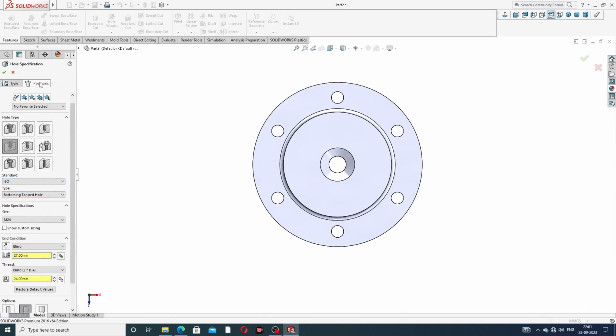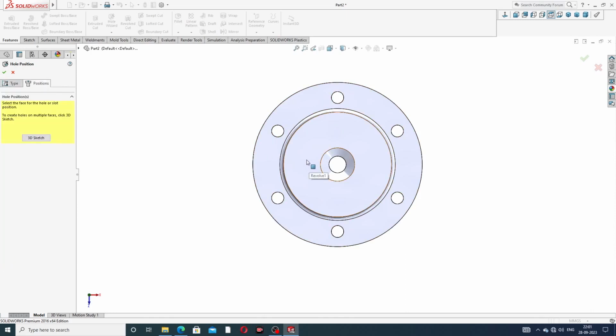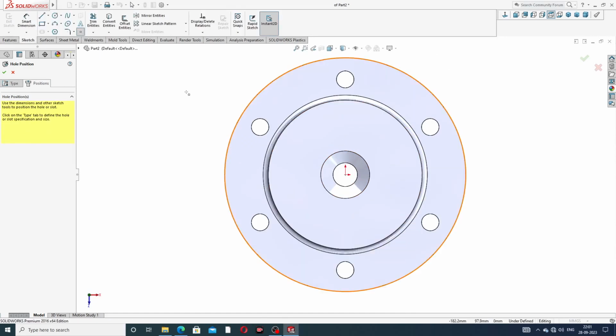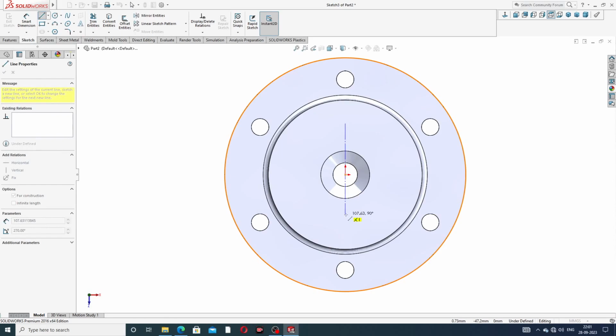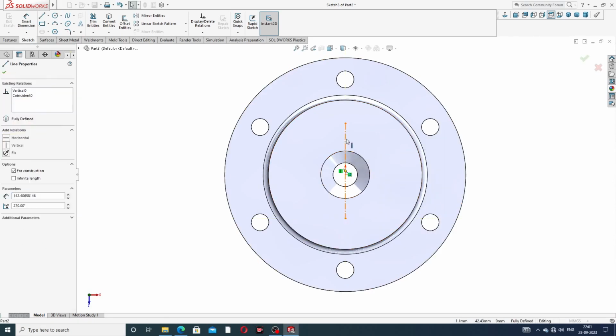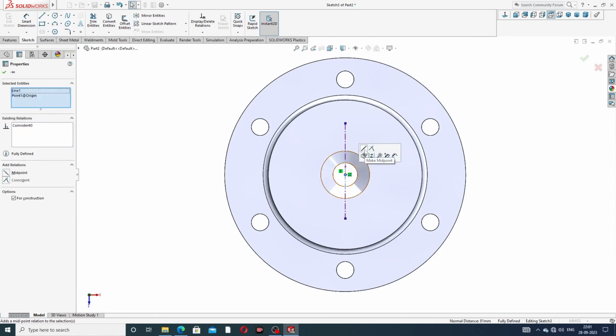And going to position, and this is sketch normal. Okay, and draw a reference line. Reference line is perfect drawing here because this uses a mid plane. Select this line and press the control button and select this point and use a mid plane.